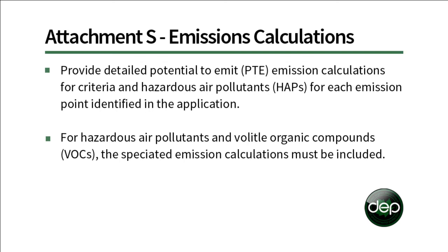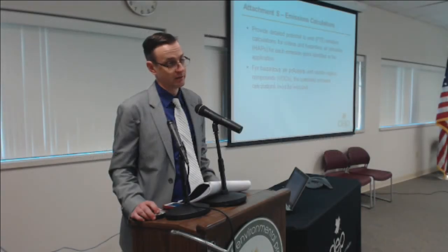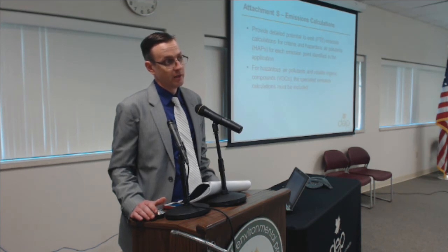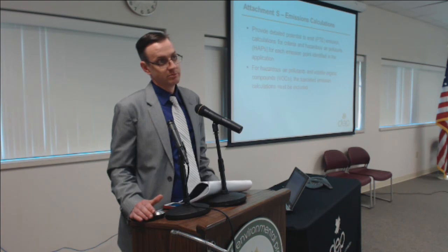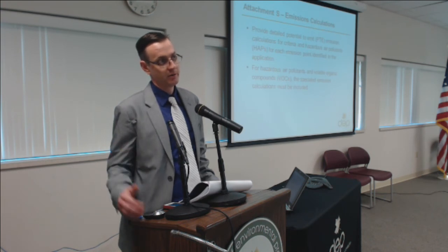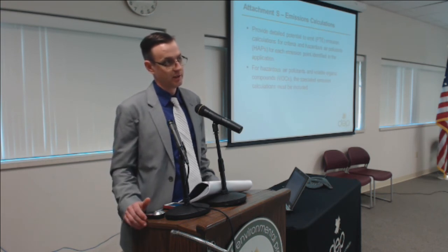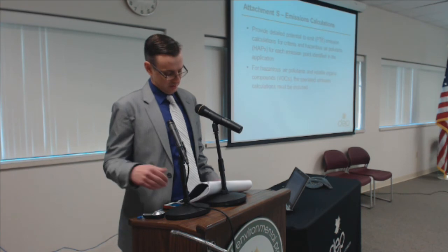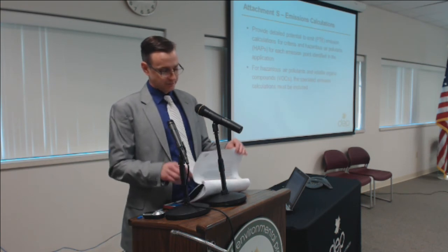The hazardous air pollutants need to be speciated. Like in this particular situation, you look at your BTEX, hexane, xylene. I mean, we don't need you to tell us that you have an odd HAP at 1/1,000,000th of a pound per hour. We want the total HAPs, and we want you to speciate out like the BTEX and the hexane, and we'll go down to that level.